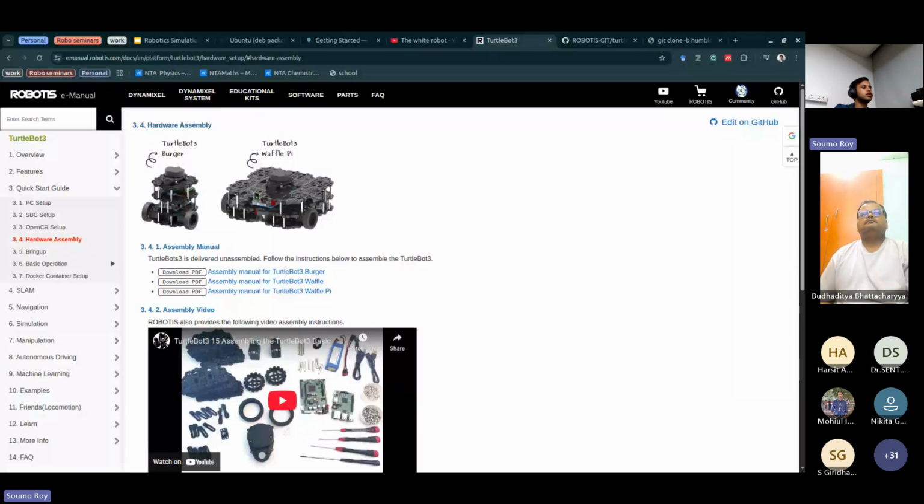And the question is, you need to think in systems. Let's say in perception, if I have to move away from this LiDAR to a camera module, how would I do that? Now I cannot get odometry from LiDAR, so I can get odometry from the camera using VIO. This is basically visual inertial odometry. So you need to know the trade-offs in systems, why you are going to take an X approach, why you're going to take a Y approach.